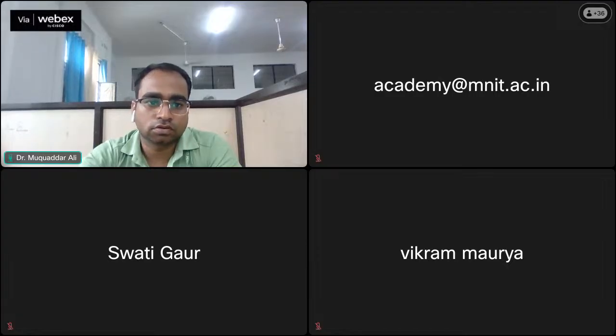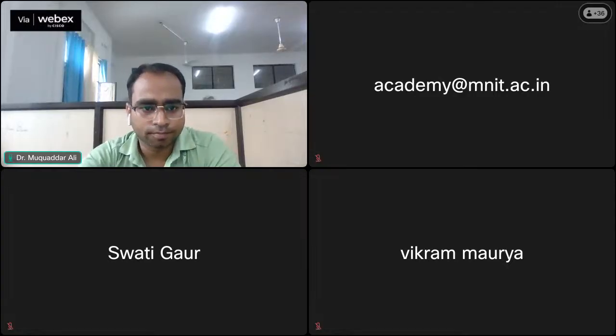Whereas when you are simply doing Control C and Control V, it has created another object with the same operations, but both of these objects are not linked. So I'm creating it like this, and now I'm giving it a rotation along z axis of 90 degree. Click OK.